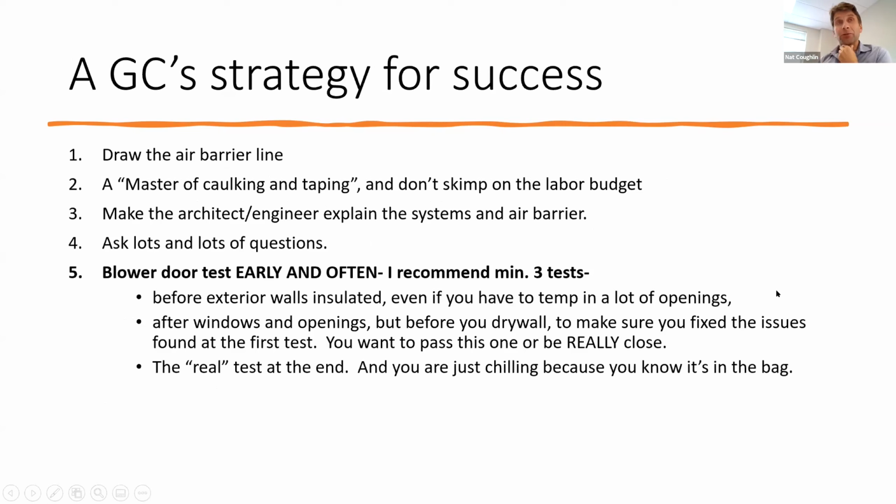Strategies for success. As we start a new job, we've been thinking a lot about this because we're starting a new one next week. One I actually got from the class I took down at Auburndale Builders is to take your plan set and take your pencil and draw the air barrier line on details around windows, at the foundation, at the roof to wall connection, because you'll often find that you can't draw it because you can't figure it out. And that comes to all those questions.